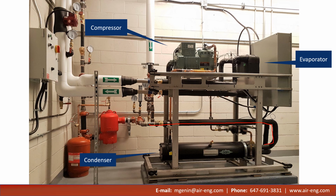So let's try to identify some of the refrigerant lines and follow those. The easiest place to start is with the compressor. We have the suction line, and again that's the low temperature, low pressure side, so we expect it to be insulated. And we have the discharge line, which is a high pressure, high temperature side, and it's non-insulated. This discharge line runs along here, in case it's not obvious, and down into the condenser.